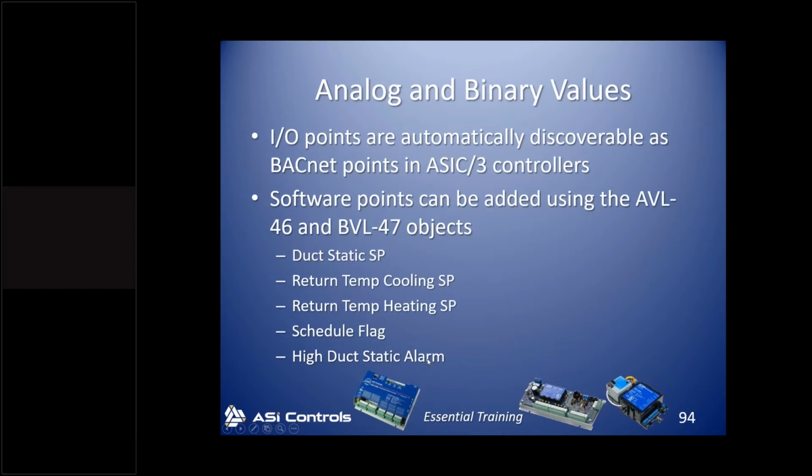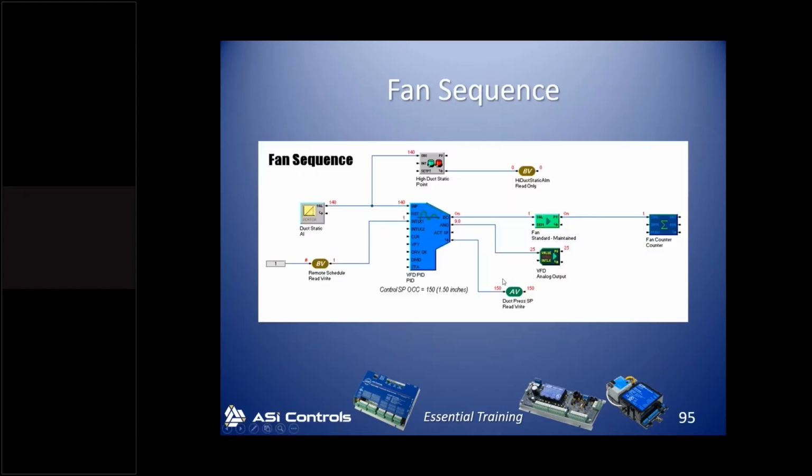So when the static pressure gets too high, then we can trigger an alarm that IntelliFront can show in its alarms app. So I'll show you the sequences that we're going to program, and then we'll actually go back, put the points in our controller, and then actually do the programming ourselves.